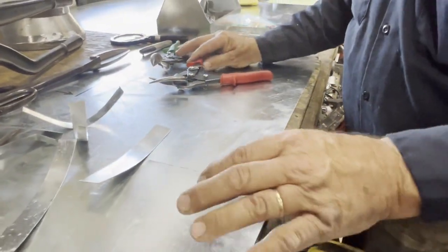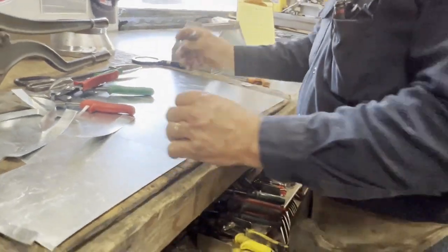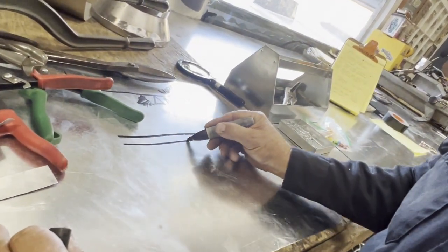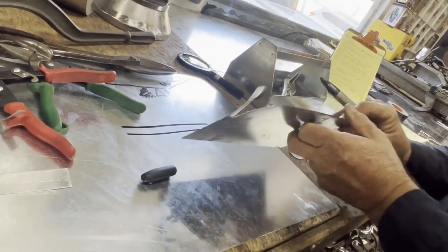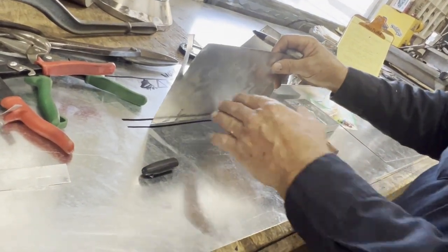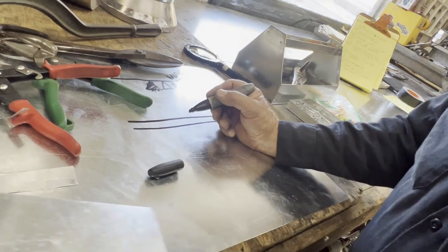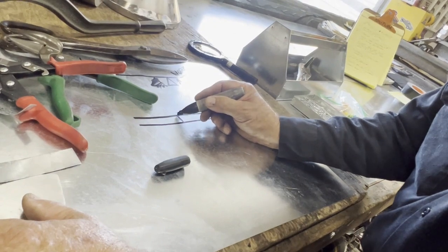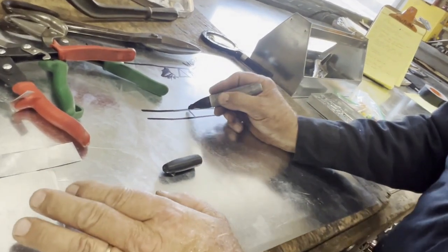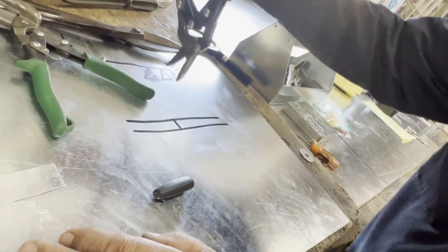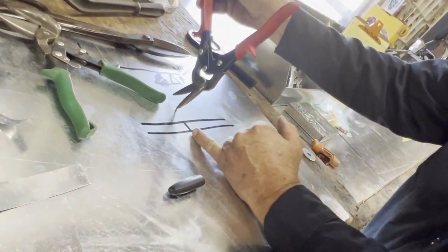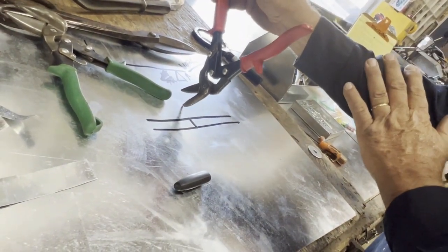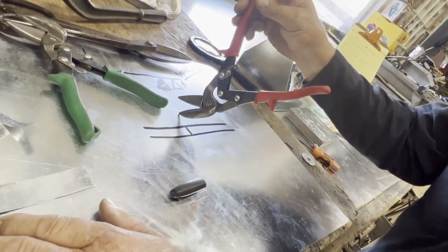So let me just give you an idea. Let's say we have a piece of metal. What I'm going to do is I'm just going to look at this metal on the end. So we've exaggerated it for clarity. The shortest distance between 2 places is always a straight line. So if I wanted to shear this into 2 pieces, if I'm holding my snips perpendicular to the work, I'm going to be cutting in the shortest possible distance. That transfers into less strength required to complete the cut.